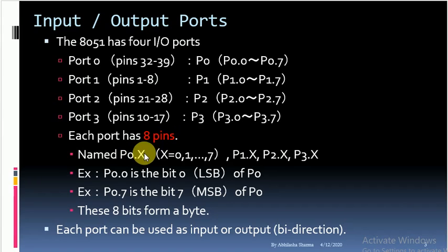Whenever you have to access a port through programming, how do we write the port pin? This is an example to define how to write a particular pin for the 8051. For example, to write a port 0 pin, we write P0.x. X shows the particular bit of the particular port. So P1.x, P2.x.